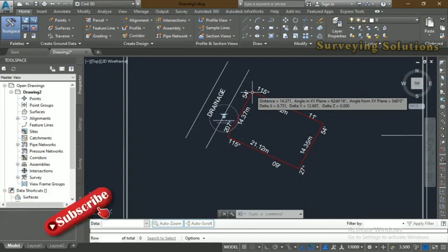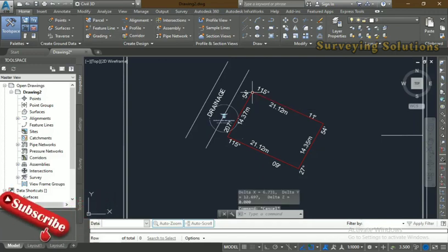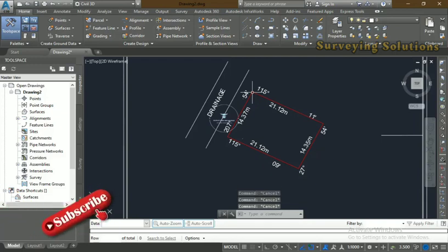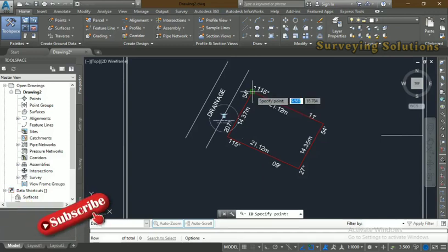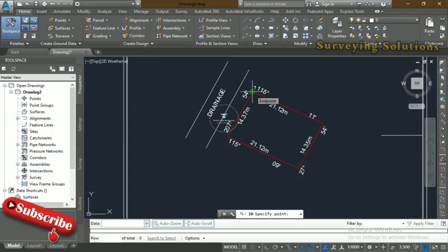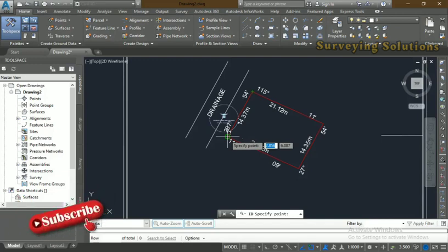So the first thing, we moved from PDF to AutoCAD. The second thing, we've tried to scale our length or the dimension to the desired dimension of what we need. Now the next thing is that we want to make sure that the coordinates are actually in order. Now how do we know that? Let's use ID. When you use this command ID, it gives you the coordinate of any point you specify. So let's say we ID this point here, because the coordinate of this point is known.